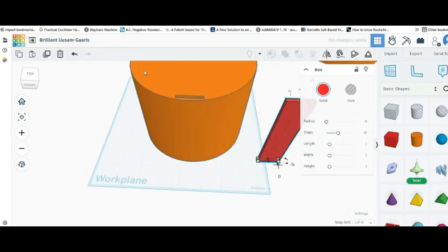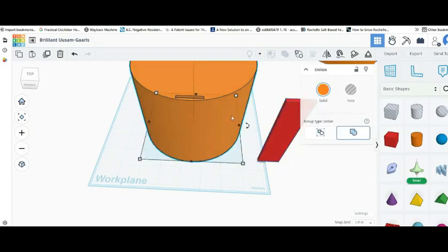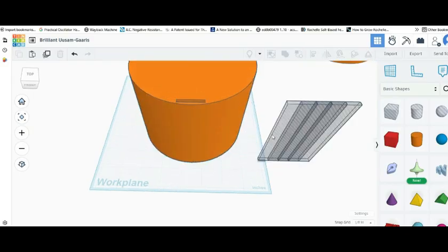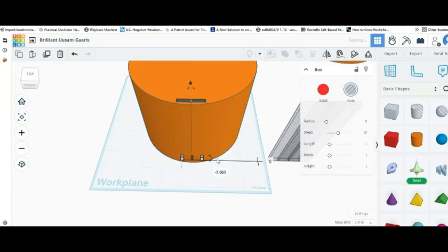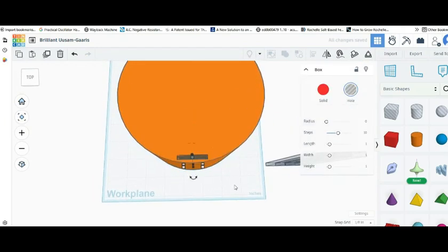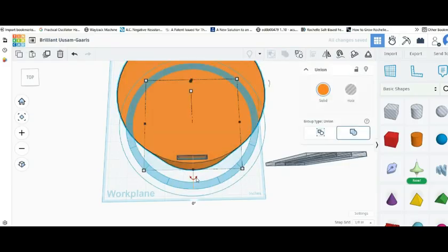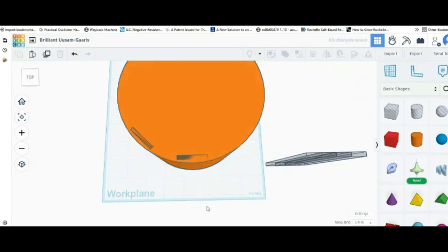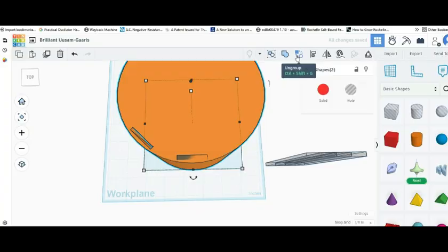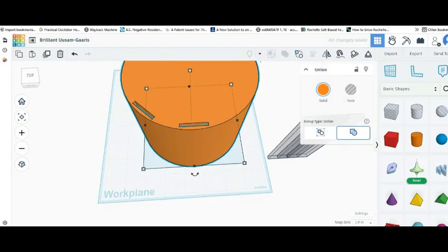So now we want to make those all around the periphery, and we're going to have 8 of them. So 360, it's 45 degrees. So we take the next one here, and we kind of just do that, and just make sure that it lined up correctly. Now it's lined up correctly. Now we rotate 45 degrees and do another union. Okay, now we got 2 slots, so I'll finish that and get back to you.